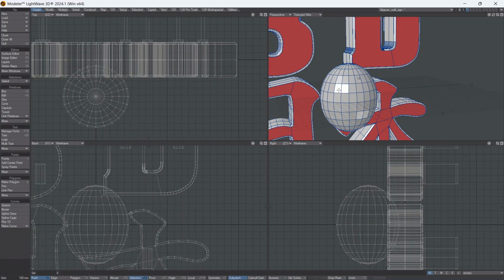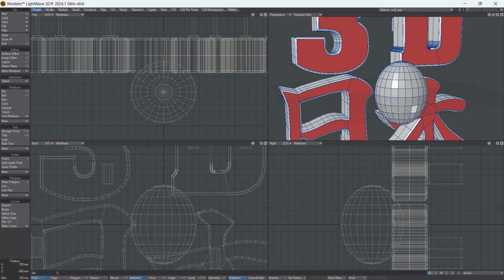So let's talk about making selections. Do it over in the top viewport here. If you use your right mouse button, you can draw a lasso, and you can lasso some. Currently, points is selected, so when I let go, we get a bunch of points selected. Now, if I go over them again, they get deselected. Another option for deselecting is to just double click in an empty space, and it'll deselect everything.